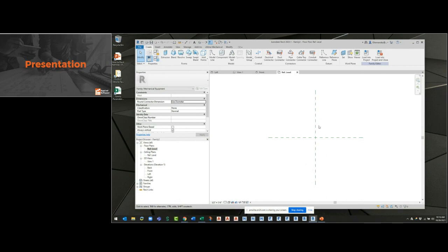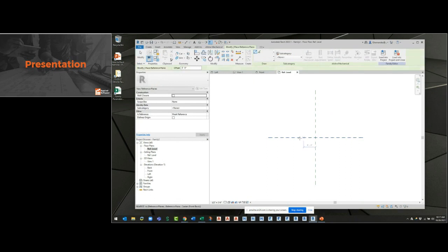Okay, so where I get started here, once I've checked all my settings and configurations so far, I can then use what we call the reference plane command to start building the bone or the structure here, right? The bone work or the framework. Reference planes, again, are finite planes. So what I'm going to do is generate two reference planes here vertically and then label them.